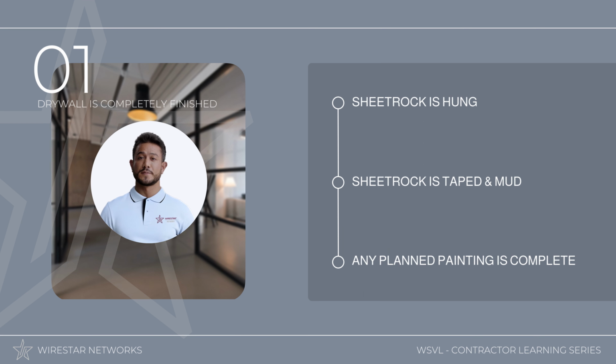Number 1. The most fundamental requirement is that the MDF is sheetrocked and painted. Electronic equipment cannot be installed prior to painting under any circumstances. To mitigate any risk from drywall crews working around the expensive network equipment within this room, it's crucial that the room is hung, floated, taped, and painted prior to our arrival. If this hasn't happened yet, your MDF is simply just not ready for the equipment to be installed.